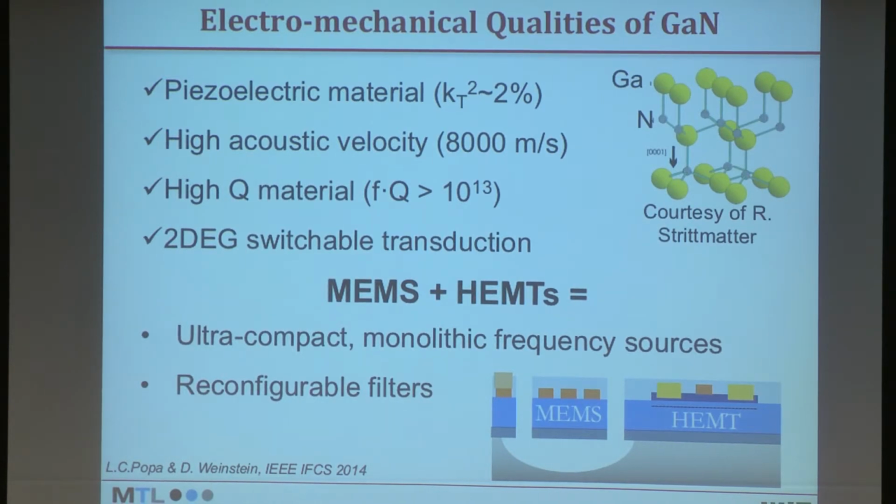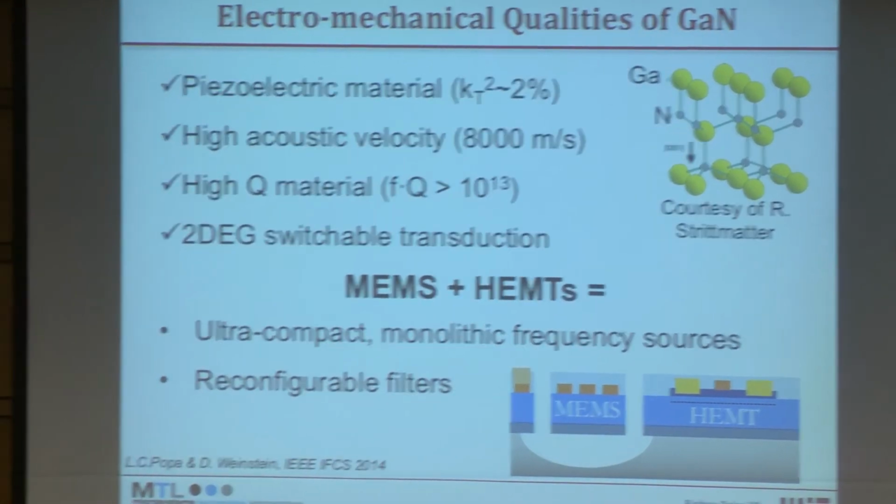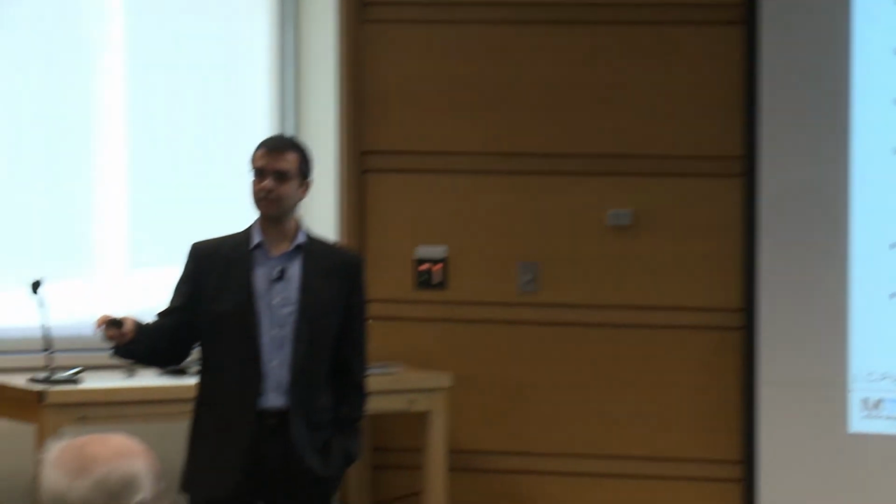So we said, okay, let's use that. And it also happened that in our group we had Laura Popa. I'm pretty sure most of you know her. She was working on developing these lateral-extensional mode MEMS resonators inside GaN MMIC technology. And what she achieved is that she can finally make these resonators side by side with HEMT transistors. So, in the same idea as we had in CMOS, we can now get a MEMS resonator side by side with circuits.